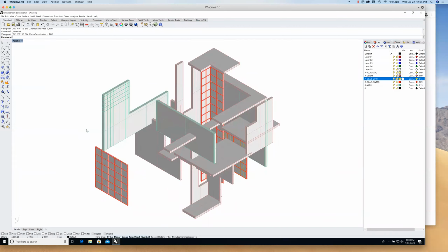The whole point of an isometric drawing is that everything is to scale, everything is parallel, and everything adheres to either the vertical or 30 degrees in one direction or 30 degrees in the other direction. That's the standard. And so we're going to just follow the protocols here.